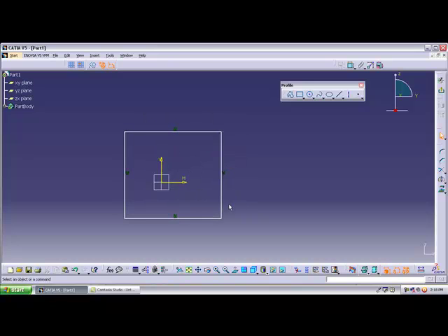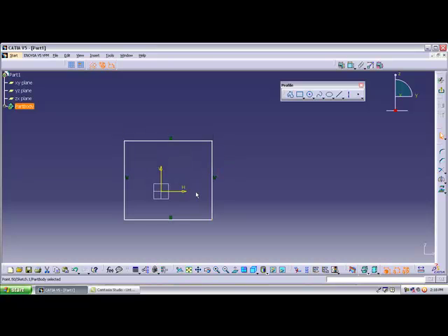So right now we want to apply the dimensional constraint. Dimensional constraints means we fix this line to 120 and this line to 60. If we don't apply the dimensional constraints and I move this line, what will happen? The line length is moving, which means it doesn't have a fixed dimension. The monitor should have a dimension of 120 by 60. Is it perfect now? No. So how do we fix this line to 120 and make this line 60? That is called the dimensional constraints.